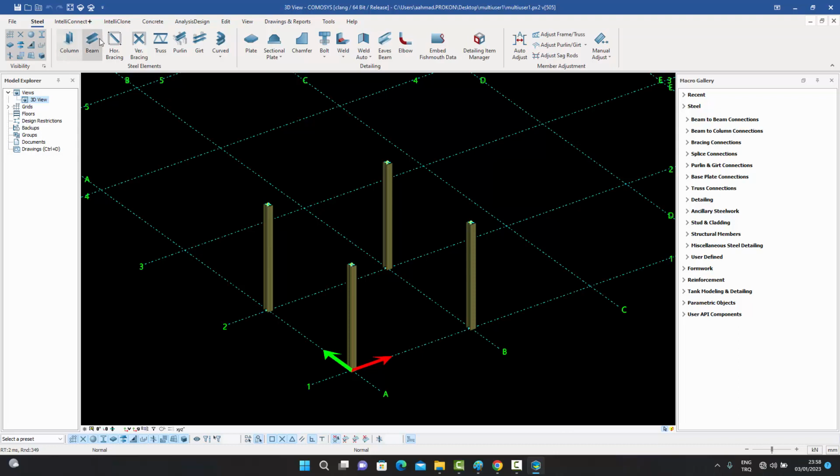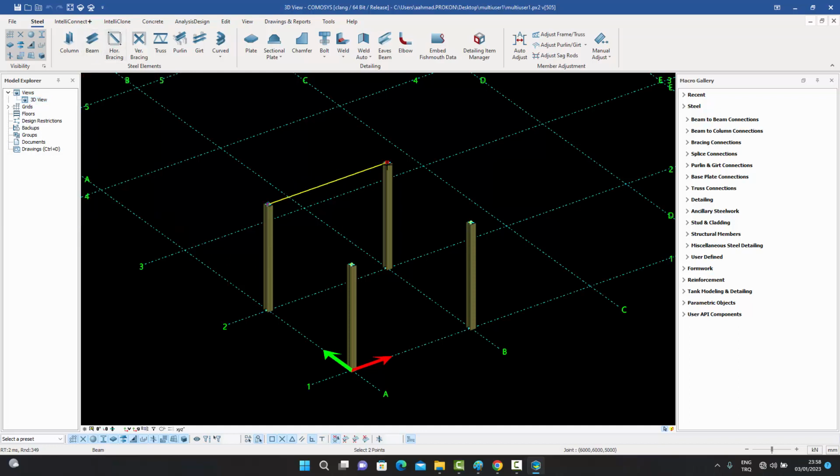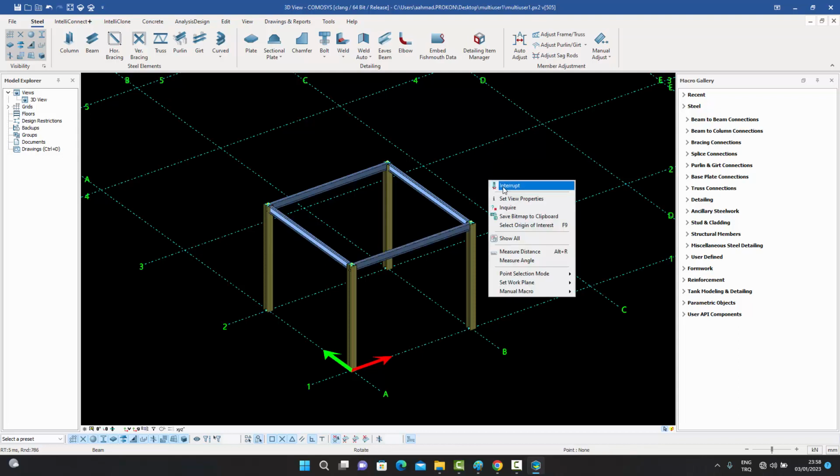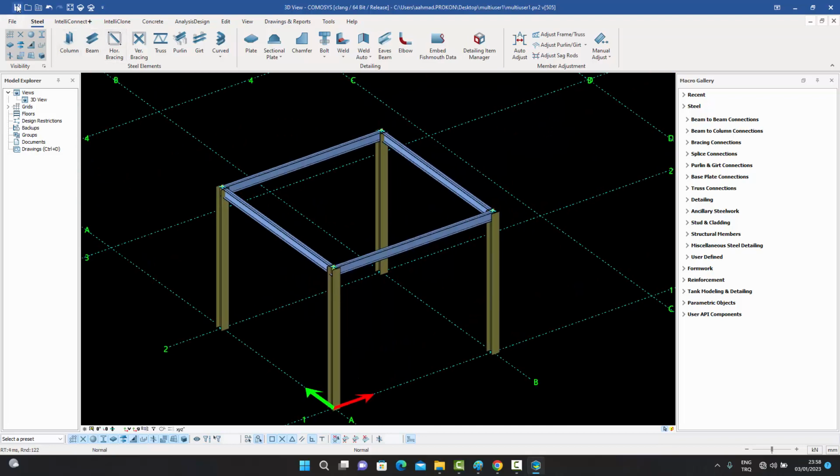Now what I can do is, this is user 2 if you remember, I can add a few beams over here. And okay, this is my contribution to the model now. And when I do that, I can save my model. Now if you notice over here, it says load updates from server and save changes to the server. I can use my own save. This is on my local machine, but I still haven't saved it to the server.